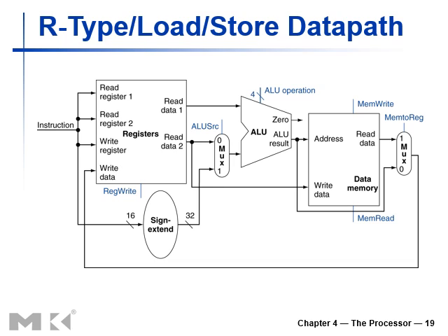Now this is the basic structure that we discussed earlier in our example, and this structure is used for the R-type, loads and stores for the data path. This is not a complete diagram because the fetch unit is here in this direction. We've got instruction memory and some dedicated registers here, and the adder, if you remember, that updates our instruction memory. We add 4 to the program counter value in order to generate the next address.